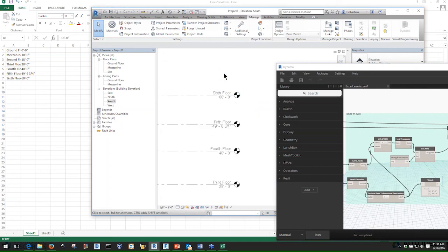This takes a little bit of time to figure out, but at the end of the day, once you have this set up, you can use it over multiple projects. This is an example with levels, but you can do this with rooms, room data sheets, furniture, lighting. You can name anything within the Revit interface. Anything that has a parameter can be managed or controlled from within Dynamo. The fundamental difference is that you're doing this a whole lot faster from within Dynamo.